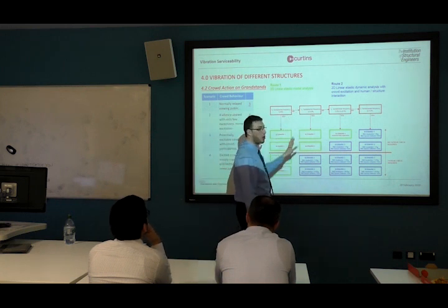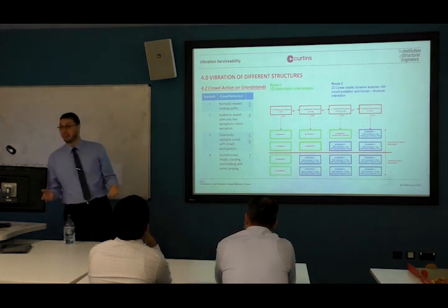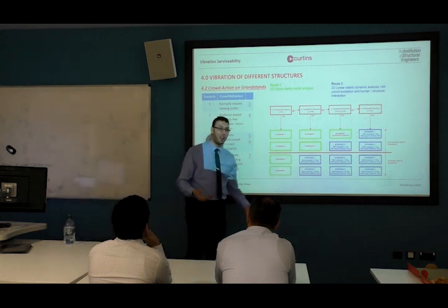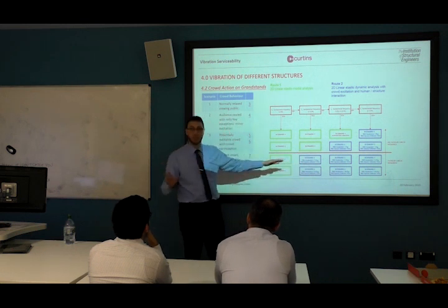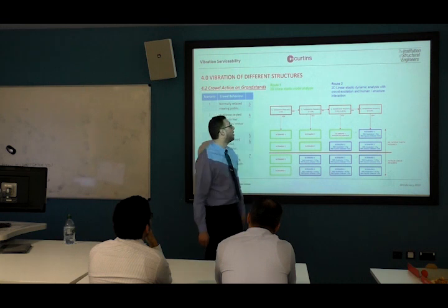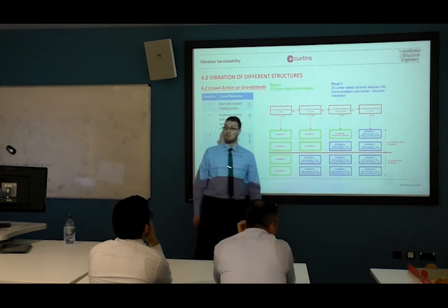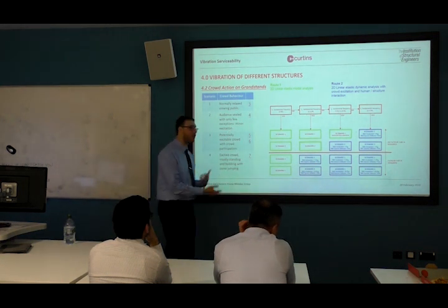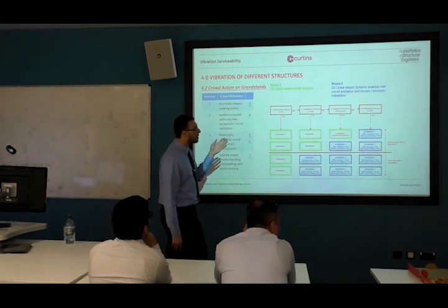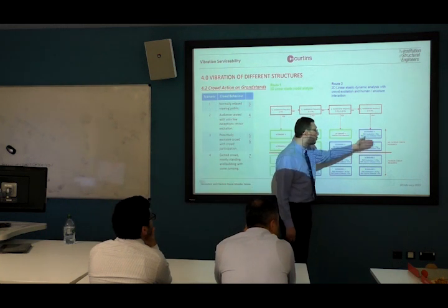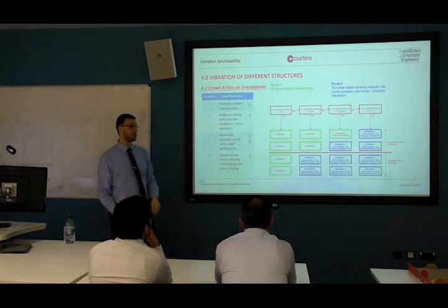It is okay then for scenarios 1 and 2, but we've already said that scenario 1 is maybe almost someone sleeping. Scenario 2, it's not a lot of dynamics going on, but you need to do modal analysis and apply the load to check for scenarios 3 and 4. Is it between 3 and 3.5? Then it's acceptable for scenario 1, which is not a lot. And then for scenarios 2, 3, and 4, you need to do the actual time history analysis. But if it's less than 3 Hz, then you need to do all types. For all scenarios, you need to do your time history analysis.